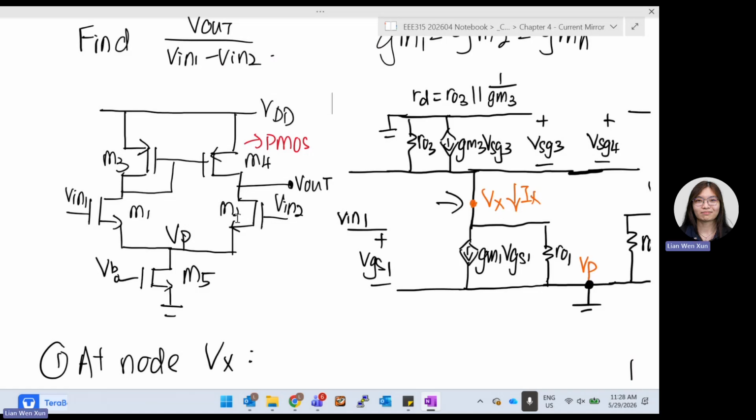What happens is the gate and the drain are connected to M3. So this is your gate. You can directly connect to here. That's okay. And then your drain, we haven't connected somewhere. That's also fine. But in this way, maybe some part will be floating. Maybe the connection is not that nice.